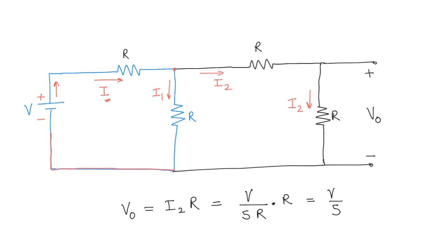These blue resistors are one of the voltage dividers. They were supposed to do a voltage division of half, and this voltage divider was supposed to do another half, so the output was supposed to be 1/4 the input voltage, but now we have got 1/5 of the input voltage.